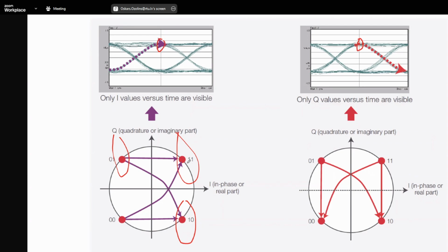So yeah, this can happen and is happening, and therefore it's very important also to adjust transmitter skew and receiver skew in experiments. But in practical systems, they actually calibrate transmitter circuits for skew values. So they know what the skew is, so they can fine tune it in the ASIC when delivering the signal.